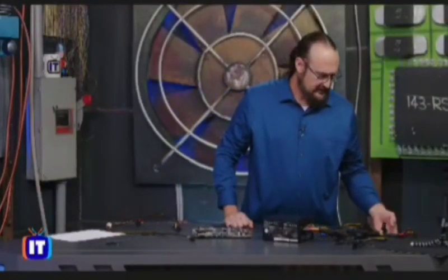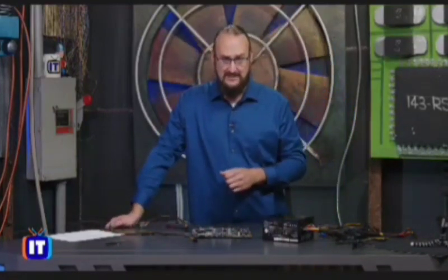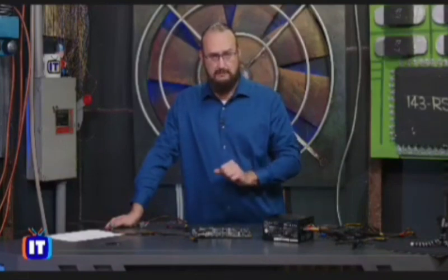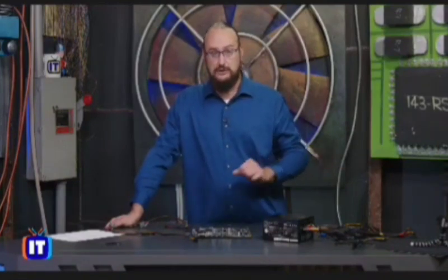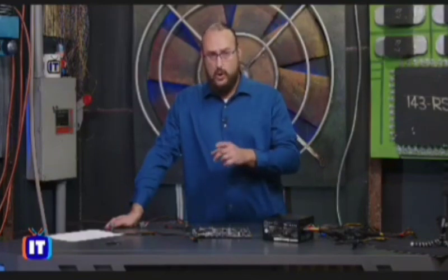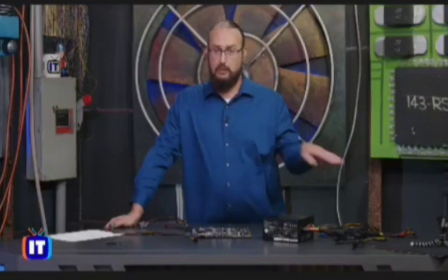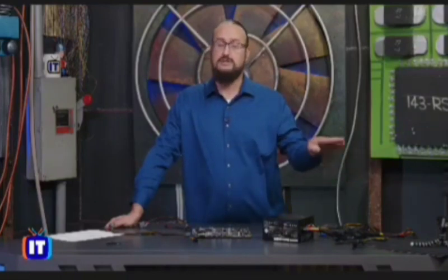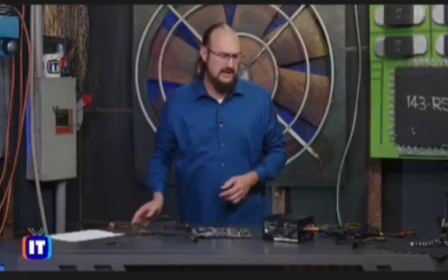Some of the older connectors that I don't have on this power supply that I would be aware of. There are more legacy connectors. For instance, there's a 4-pin Berg connector that would have been used for floppy disk drives. There's also Molex connectors, and Molex connectors would be used for things like old SCSI drives, old parallel ATA drives, and more importantly today, we still use them. We can use them, and we can daisy chain system fans to them too. So also know the Molex connector.